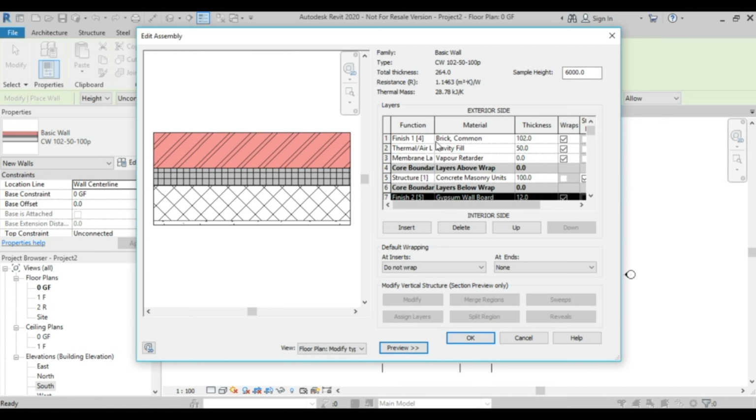And accordingly, you can see there are 6 lines that we can work with. It's the exterior line of the whole wall or the interior line of the whole wall. If you took the thickness over here and divided by 2, it's the center line of the whole wall. That's 3 lines. Another 3 lines would be the exterior part of the core, the interior part of the core, and the center line of the core. So we have 6 lines to work with.